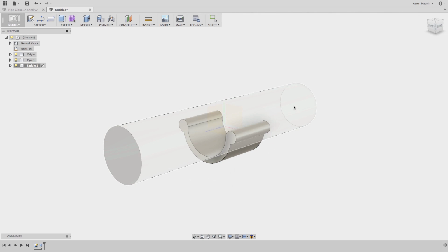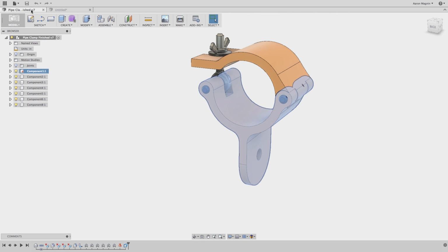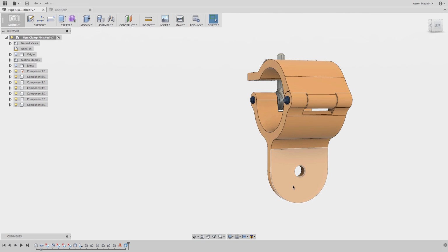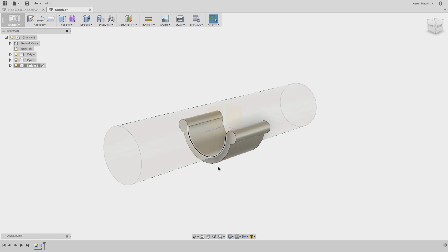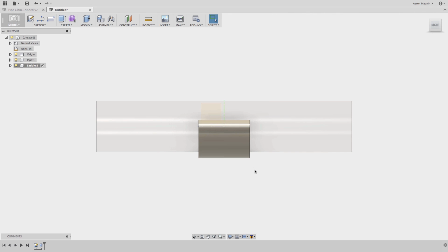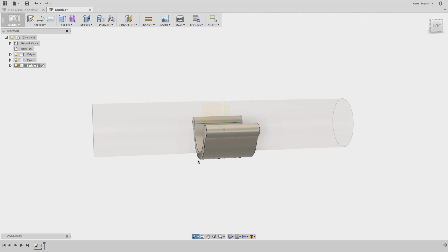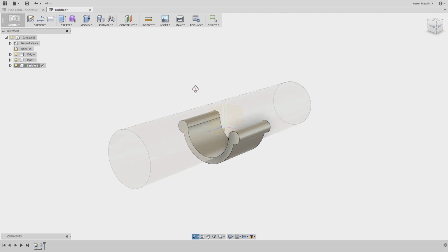The next thing I want to make, and we'll take a look at what we're going to be adding next, is this bottom piece. So somewhere to attach this guy. So let's do that. Let's jump back into my design. And there's a couple different ways we could do it, right? We could sketch out a profile from the right-hand side that takes that rounded shape and comes down like that, and we could just use an extrude there. We could sketch out a square and then we could use a fillet tool to round off the edges. But in this case, I want to do something kind of special here. I do want to actually create an offset plane and then run this next feature into the saddle piece that we've built so far. So it'll make more sense when I actually get into it.